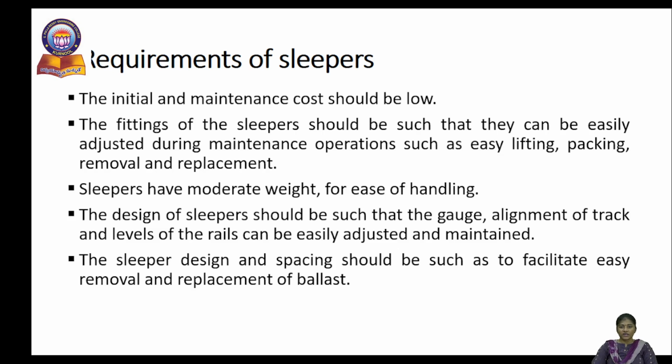Okay, so easy lifting, packing, removal and replacement must be done. Sleepers have moderate weight for ease of handling. The design of sleepers should be such that gauge, alignment of the track and levels of the rails can easily be handled, adjusted and maintained. Sleeper design and spacing should be so as to facilitate easy removal and replacement of the ballast material.